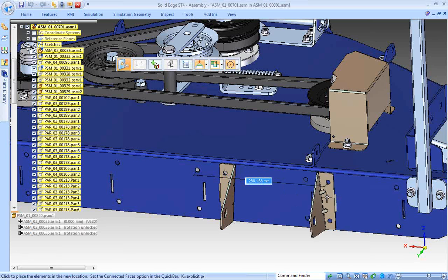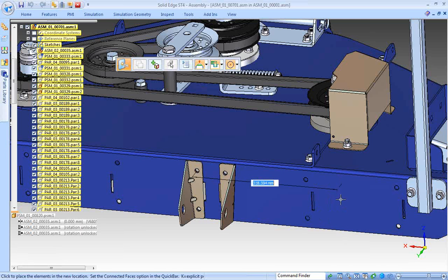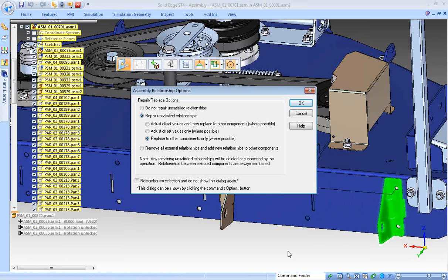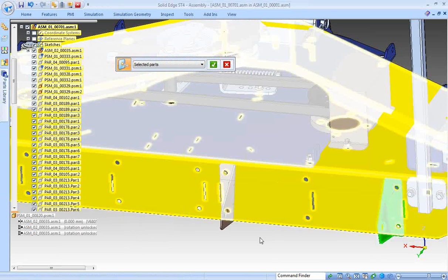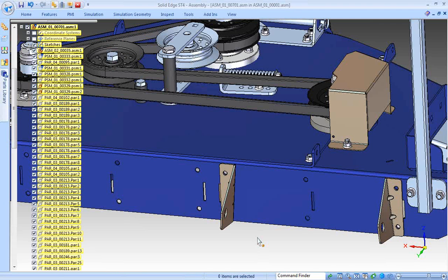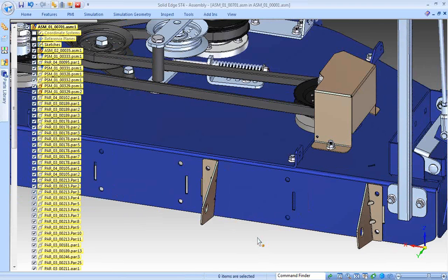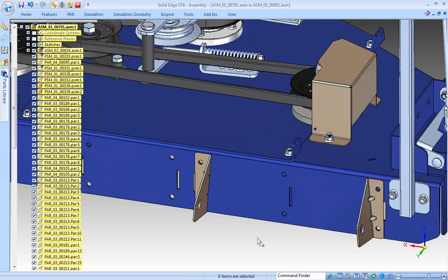So I'm dragging this component, and I want to set it to rest over here on some holes, but this part's going to get in the way. So I'm going to do Control-Shift-D, and it is going to hide that while I pick the center. And that's going to move over, and I'm going to tell it to replace where possible. And it's going to set itself back on there, just like that bearing did. It's going to set itself back there.